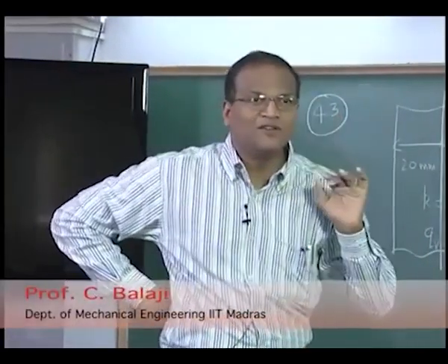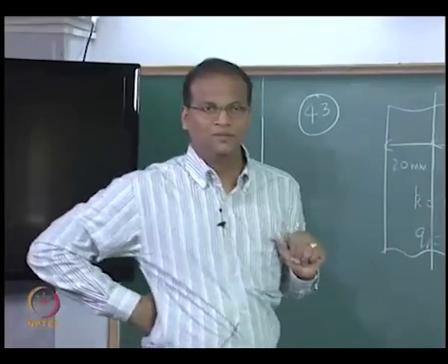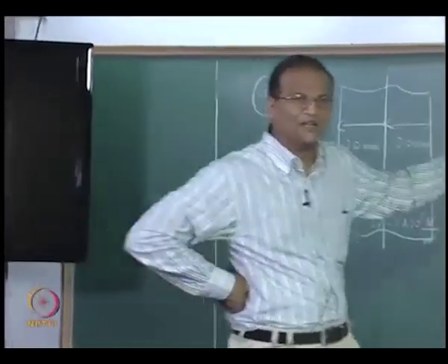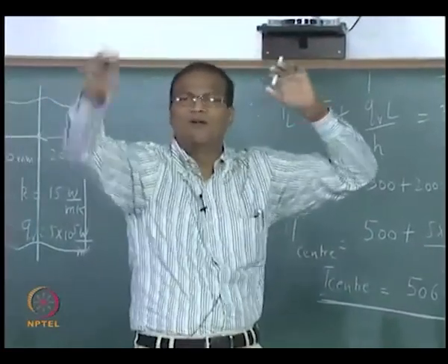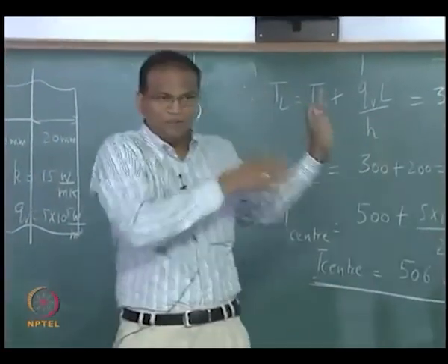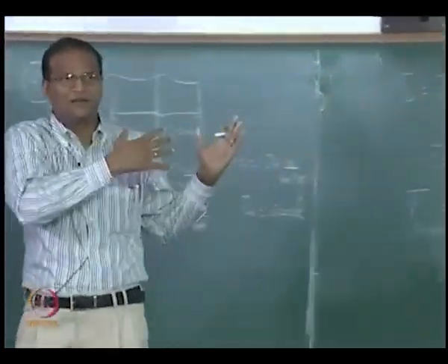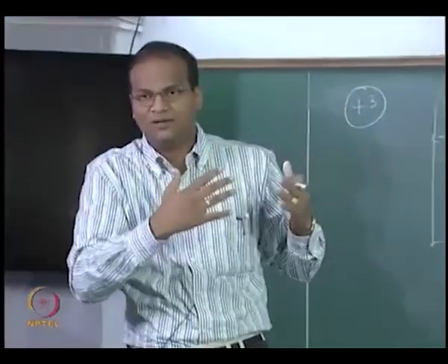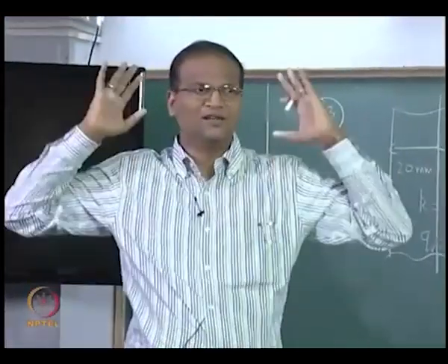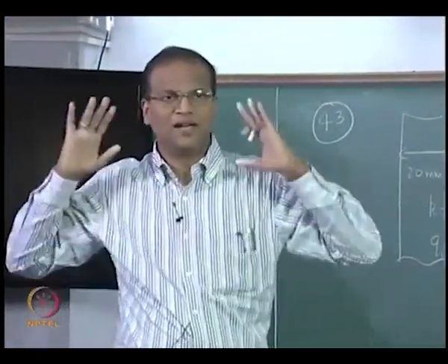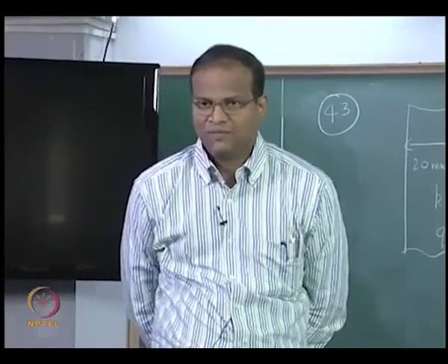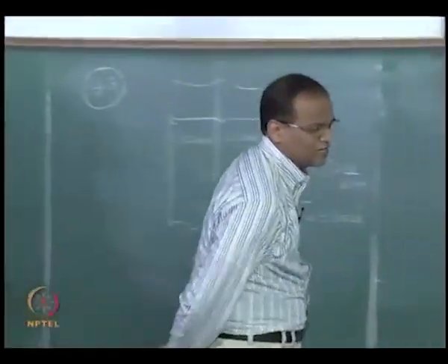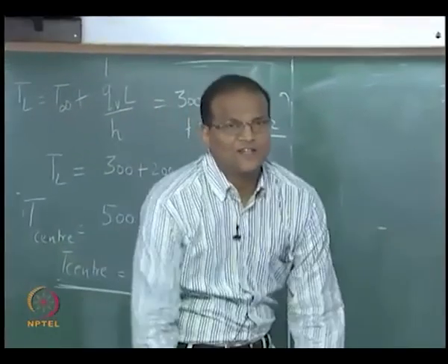This is what happens if the pumps fail. Of course we assume a lot of things, steady state and all that, but this will be the starting story. Immediately some operator will put in control rods, put in boron, they will do all that. But immediately the first thing is there will be a thermal shock. The h drops and suddenly the fuel rod temperature will start rising like mad. Okay, fine. We will stop here. In tomorrow's class we will look at extended surface heat transfer, that is fins.